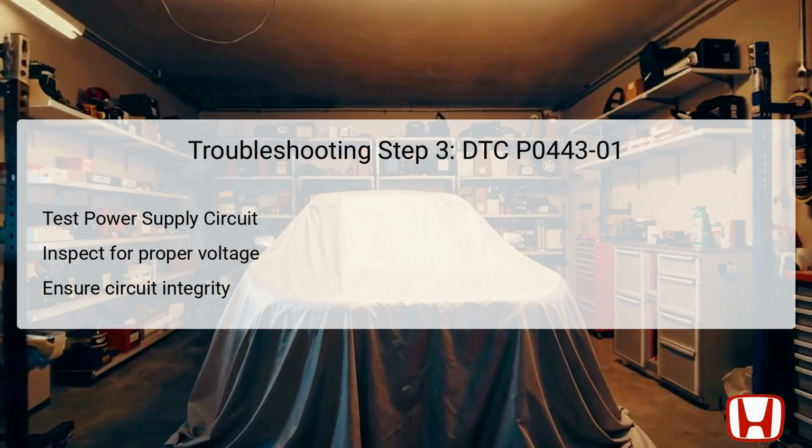Continuity tests can be conducted on the circuit to confirm the integrity of connections and check for any breaks or shorts. This step is crucial, as an inadequate power supply can prevent the valve from functioning correctly, leading to the recurring DTC and subsequent emissions issues.